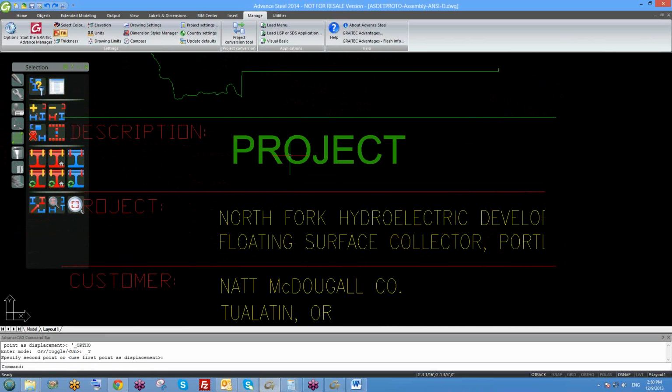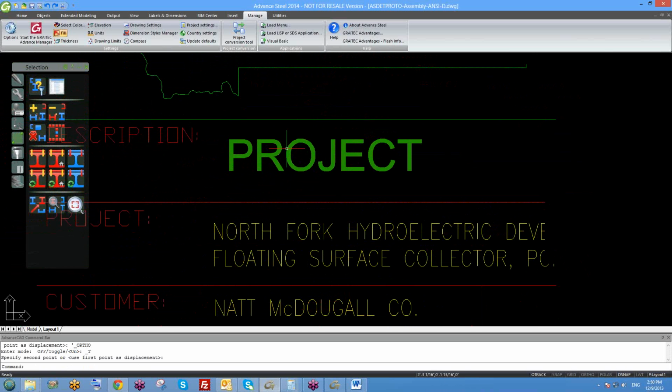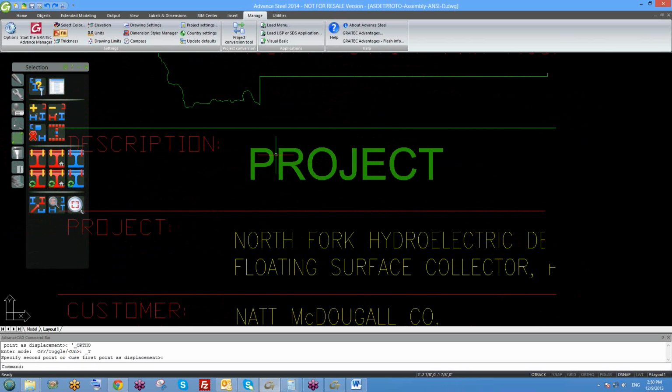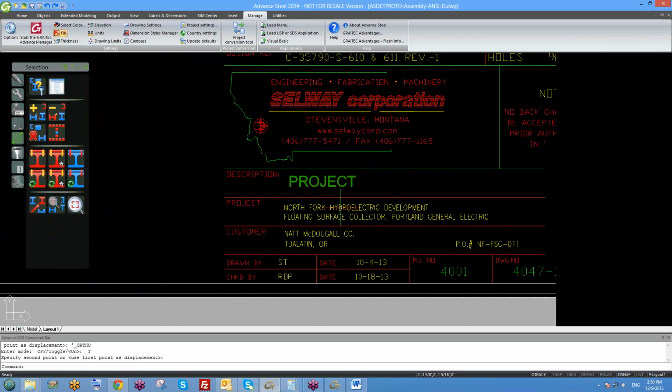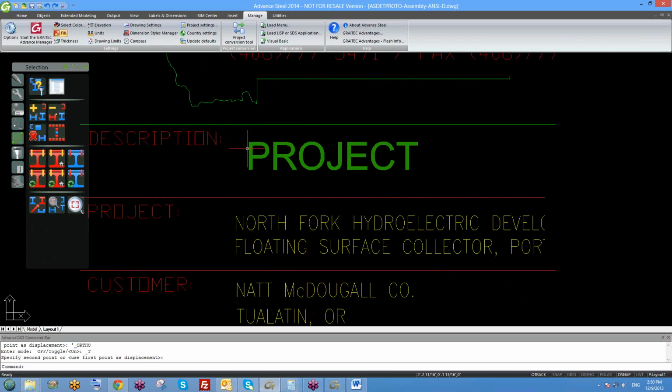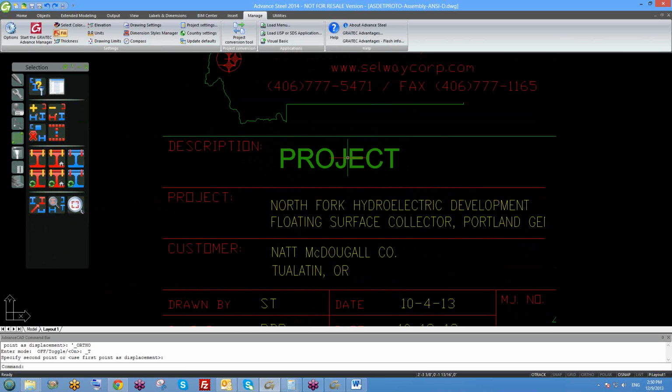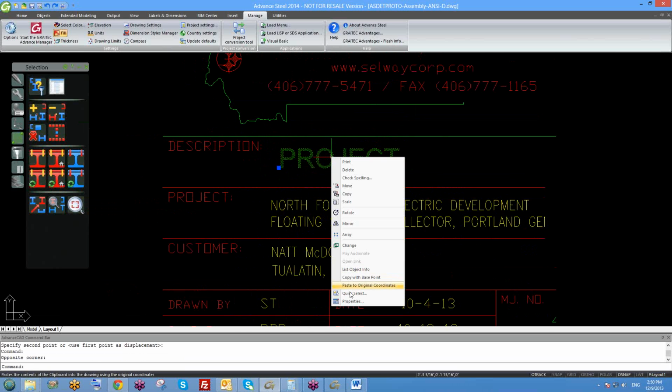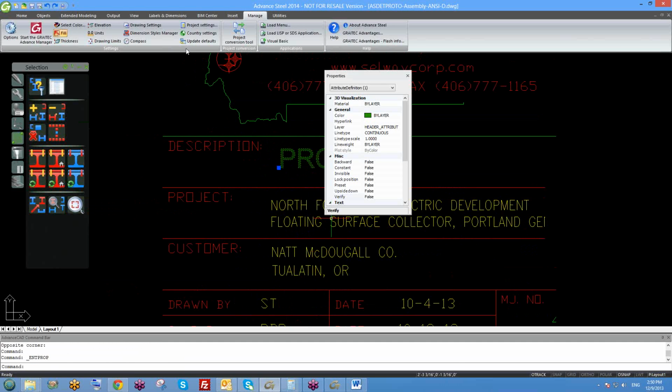At the moment, it's just a project, but it's not what you get if you generate your drawings, all right? It's an intelligent text linked to the model, all right? So now if you want to change its color, its size, and the other parameters, you can, but keep in mind, you need to use exactly the same spelling, project, with capital letters, everything, because it's something intelligent, right? So if I want to change the other parameters like the color and everything, I go to properties, right? And right here, I can change everything.